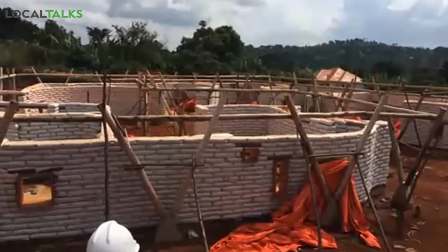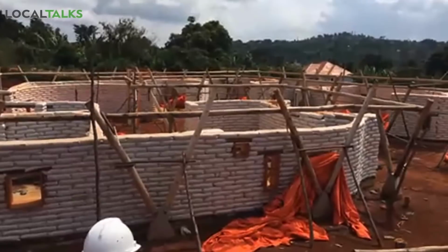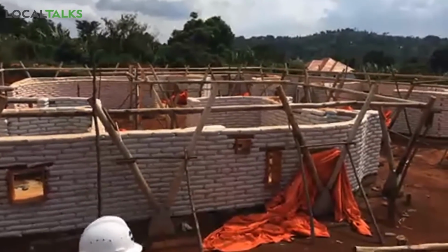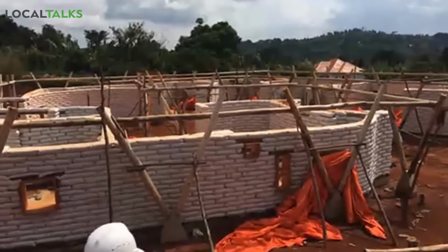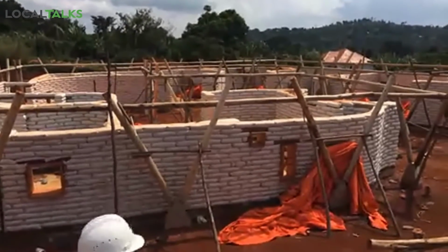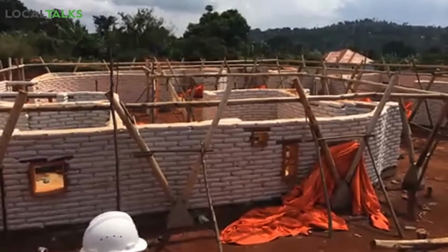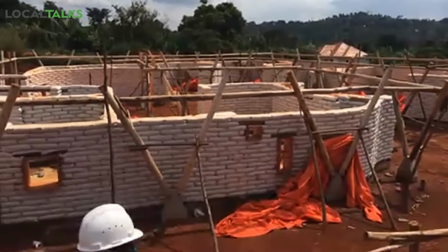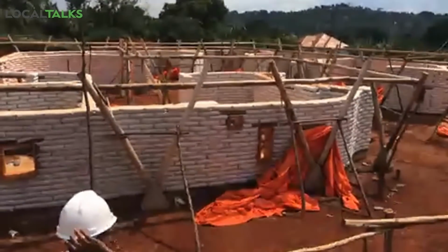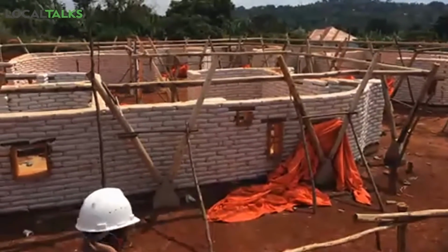The V shape has many reasons, including that a slightly tilted shape is a very interesting way of bracing a building. So we actually needed no additional bracing. You will not find any X's or diagonals that stiffen the building in either direction.